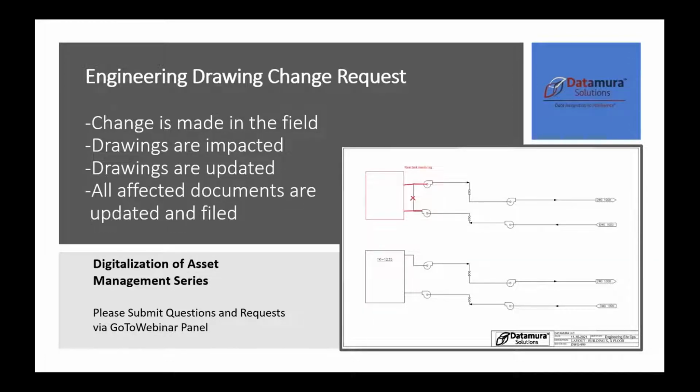So the main solution that we've developed is actually creating a formal process for document change. We call it an engineering drawings change request, or an EDCR. It's called that because we find that the drawings are at the center of most of these changes, and everything can be found through the drawings one way or another. It's an easy way of making sure that we capture everything using the drawings. However, you probably already have processes in place that we can optimize similar to this.